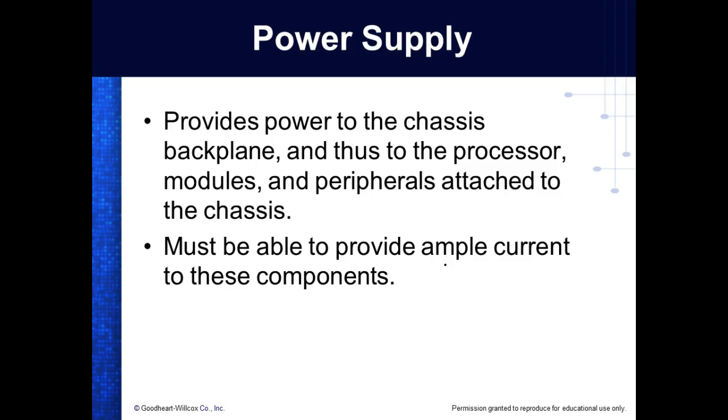So this power supply right here, which has a regular power plug on it, we plug into 120. When we usually use the term power supply, they're actually DC power supplies. Electronics does not work off of AC. Anytime you're going to have electronics, you've got to have a power supply, right? So that's what this guy does. It converts it from AC over to the DC that is designed to run the processor, the electronics. And then all the modules run off that same power.